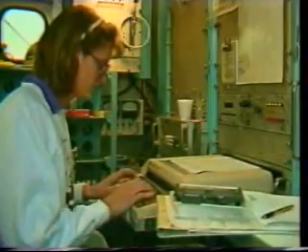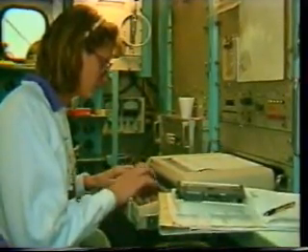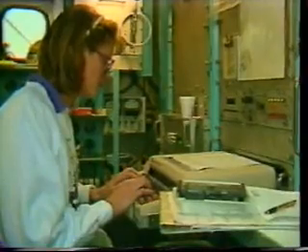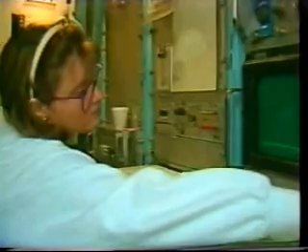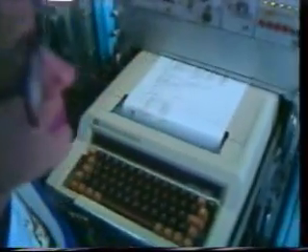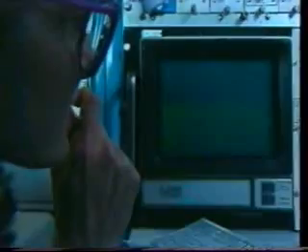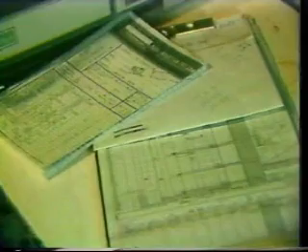Now, let's look at the logging run in more detail. Nowadays, for convenience, the repeat section is logged first, close to TD, which is usually near the zone of interest. Logging this repeat section is essential for documenting that the logging tools are operating normally and producing repeatable results. Repeats are usually run over the zones of interest so that a quick log is available for analysis. Sometimes it's advisable to run short repeat sections over anomalous intervals to ensure that the tools are operating properly.